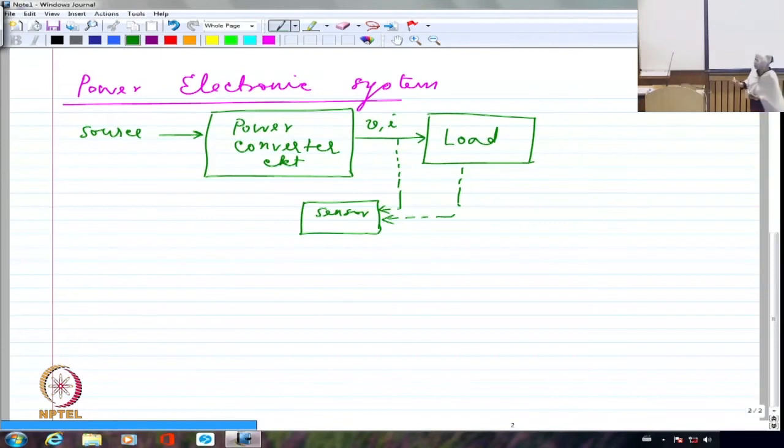I would rather call it a sensor or transducer, because a transducer converts mechanical signal into electrical signal, thermal signal into electrical signal, and so on and so forth. Invariably, I would like to convert that into an electrical signal because I am by and large handling electrical circuits. Everything converted into electrical signal will give me a lot of advantage in terms of processing them.